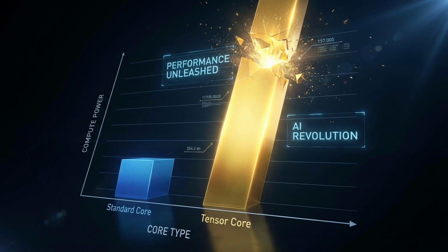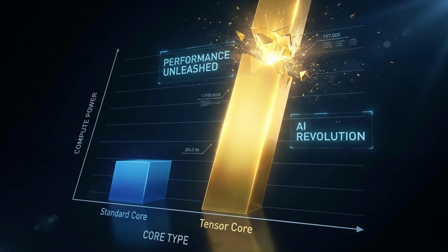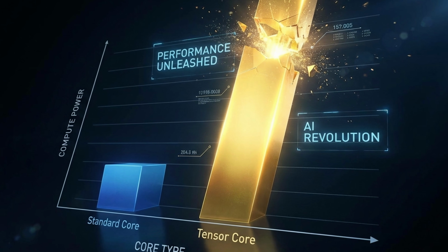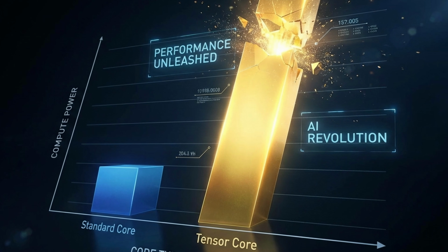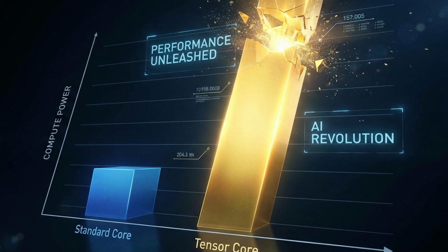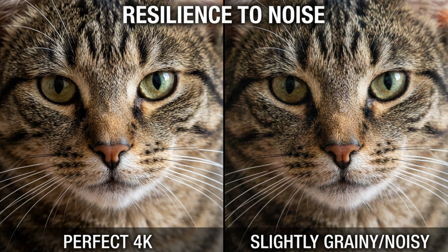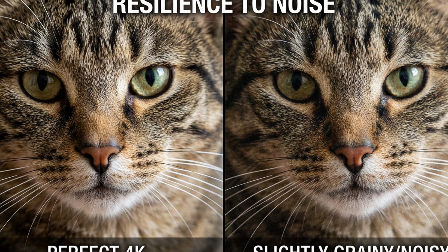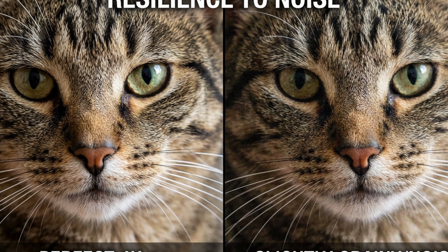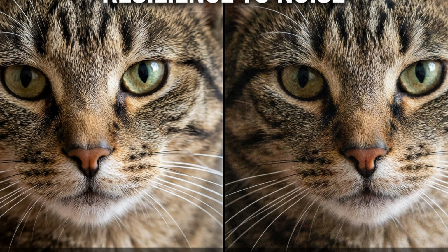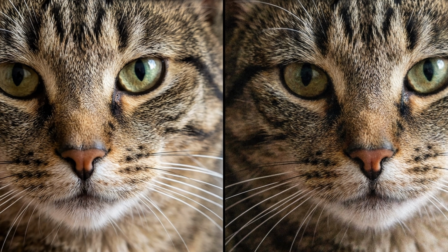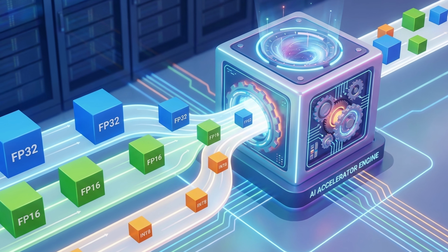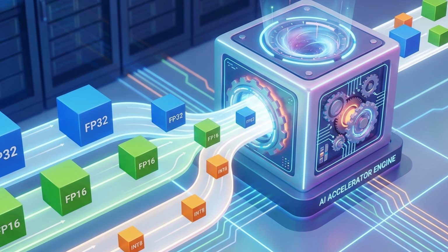By integrating fused multiply-accumulate units directly at the physical hardware level, tensor cores achieve a computational throughput that exponentially exceeds that of standard cores for computationally dense artificial intelligence tasks. Furthermore, hardware engineers realized that deep learning models are inherently resilient to mathematical noise. They simply do not require the extreme, painstaking decimal precision of 64-bit or even 32-bit calculations to achieve high predictive accuracy. Consequently, tensor cores were engineered to support automatic mixed precision training natively in the hardware.